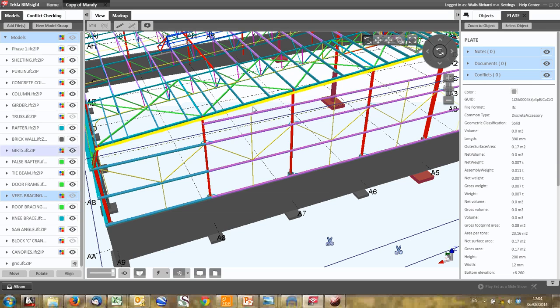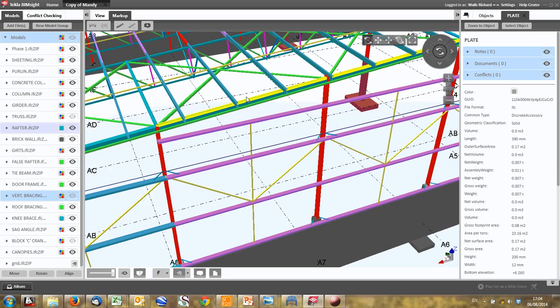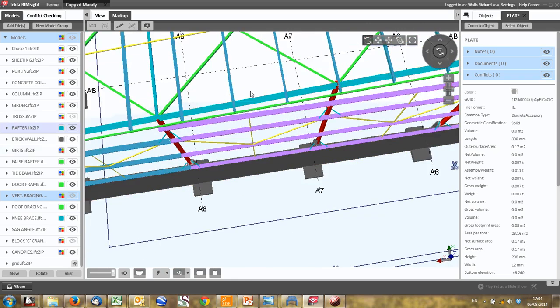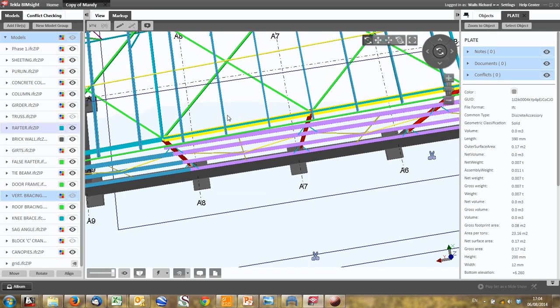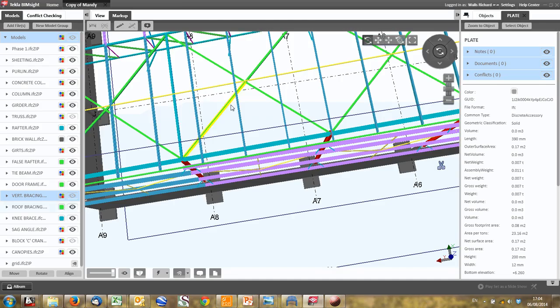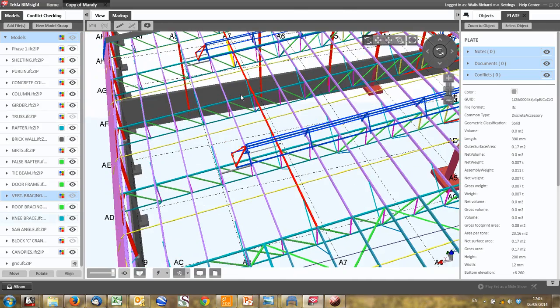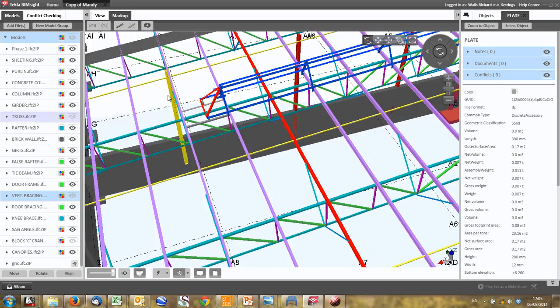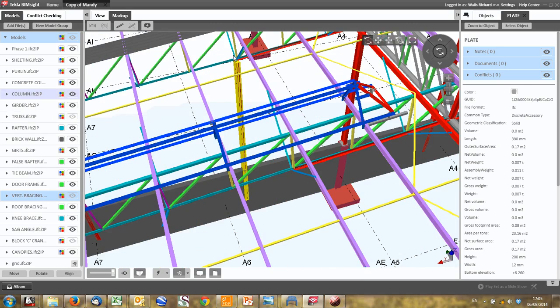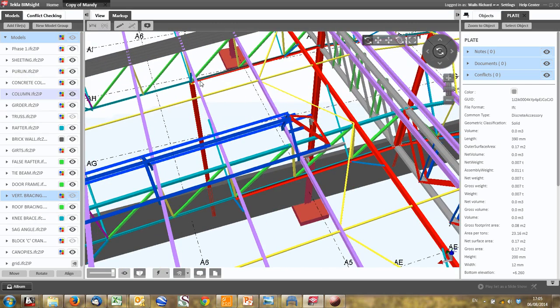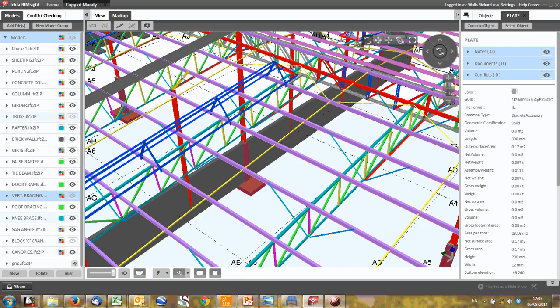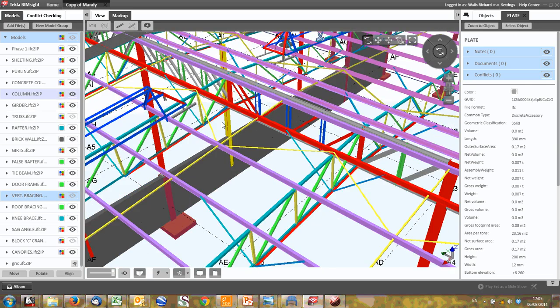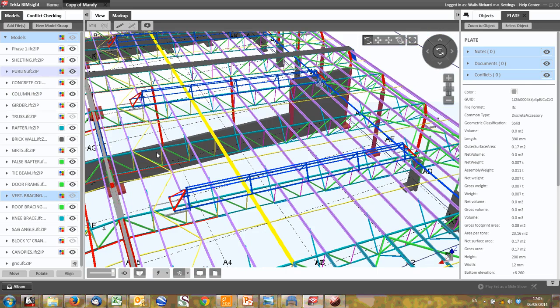Because imagine now if this gable column is in the middle. If this load pushes horizontally, where does it go? It doesn't have anywhere to go. So it just pushes and puts this beam into bending. So either you've got to design this beam for bending, or you've got to put something there and get the load across. In the middle, you'll see these ones carry almost no load. But even so, they fix the bottom of the truss, and we'd have to make sure that those little knee braces can carry any load that comes to them. Those are just temporarily in there, basically to support brickwork.